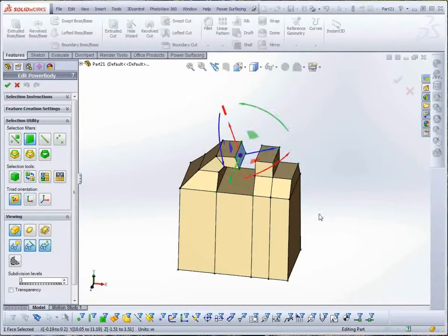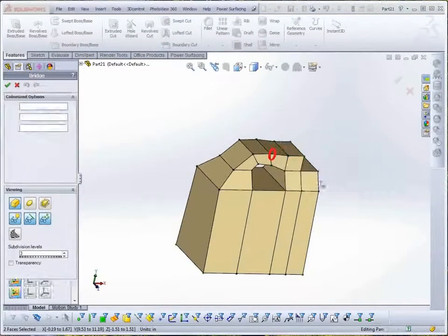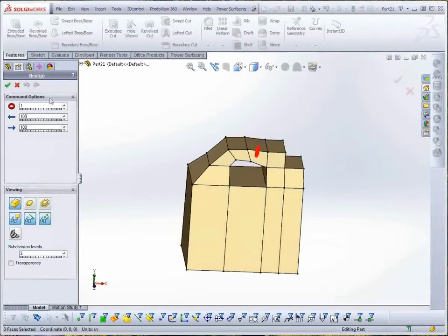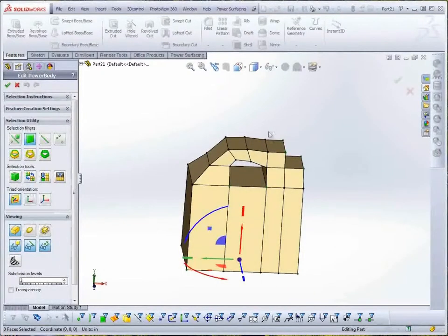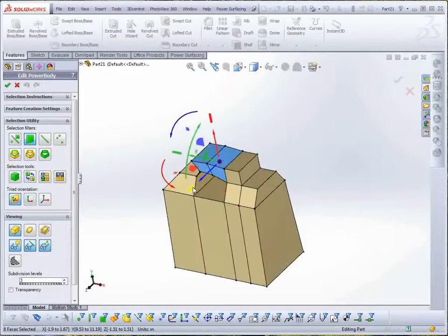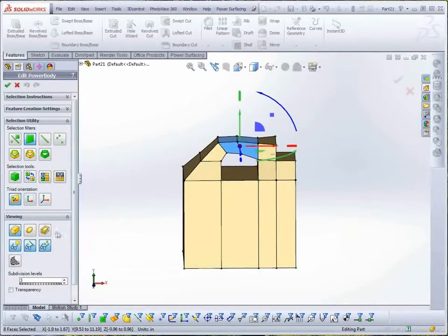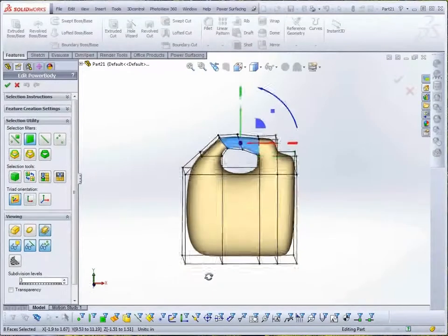After selecting my two faces with the Shift key, I'll pick Bridge from the right-click menu and Accept. This time I'll use the familiar green check mark. While I'm there, I'll select the new faces and scale them in. Just to show you what a few extra edge loops can do to the shape, I'll switch to Sub D plus Cage for a minute.